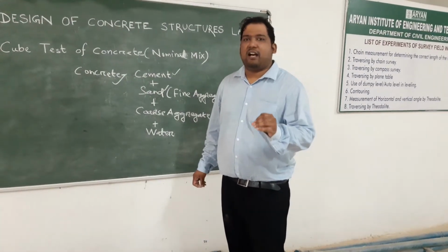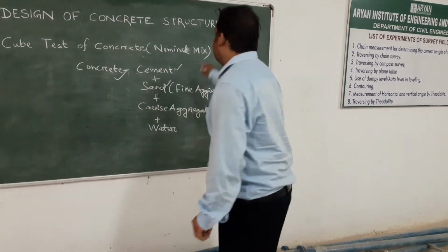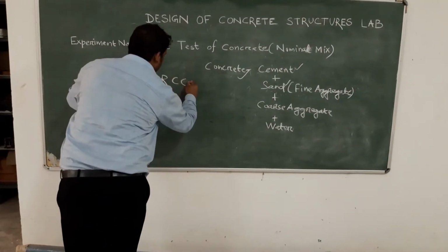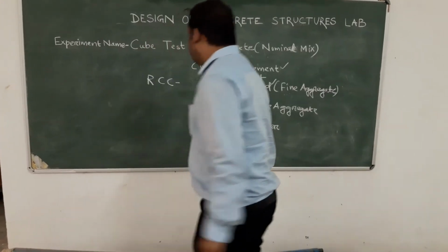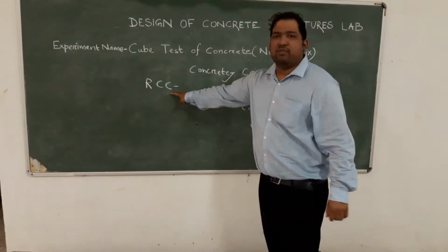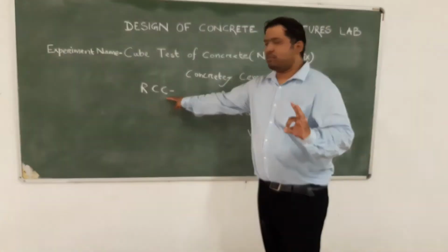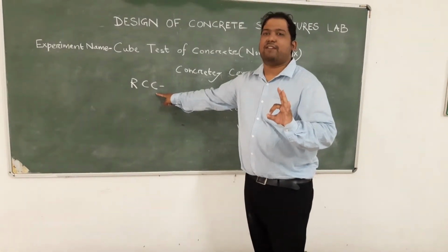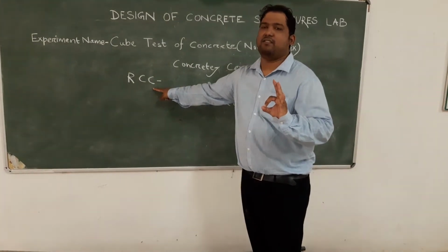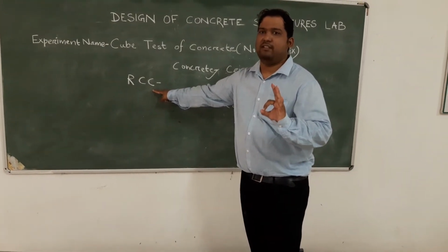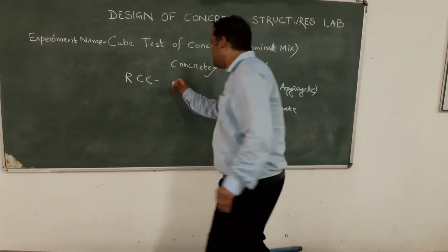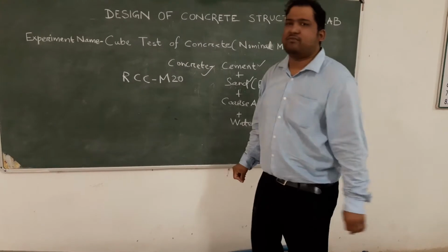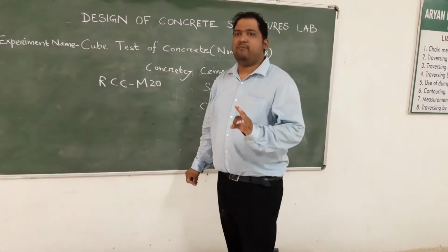For general reinforced cement concrete work, RCC work, the grade specified by IS 456-2000, that is our code for concrete, is M20. The grade of concrete should be M20.